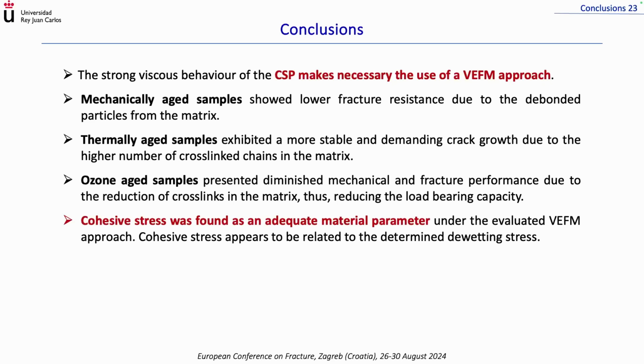And a very important one: the cohesive stress was found to be an adequate material parameter in the viscoelastic fracture mechanics approach. So the cohesive stress appears to be related to the breaking stress obtained from tensile tests.